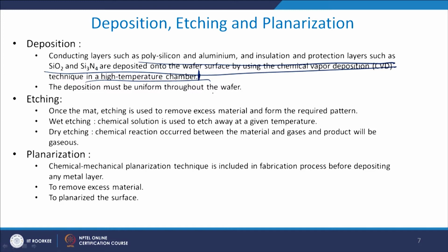So, once you have covered the area with the material across the board, then depending upon the pattern where you want the photolithography to work, if you are doing a positive photolithography, you start to remove or etch those areas through which you want the light to go inside, right, and you do that easily using either dry etching or wet etching, right.